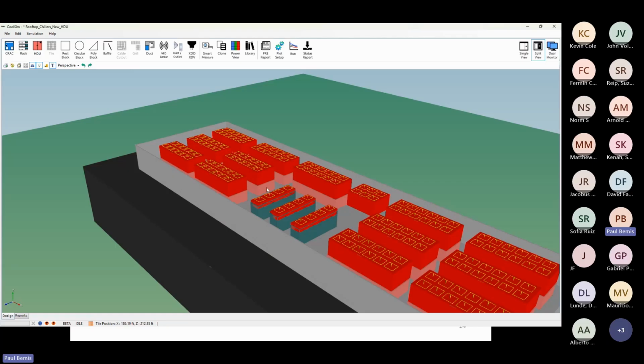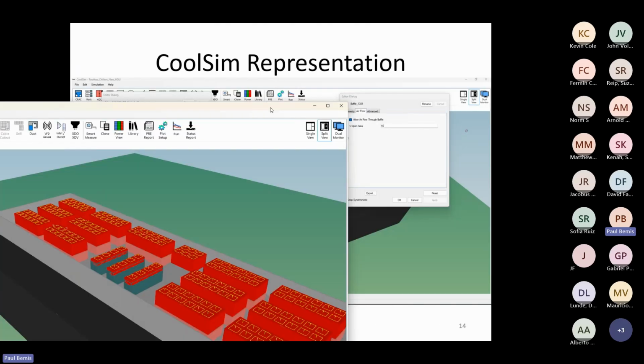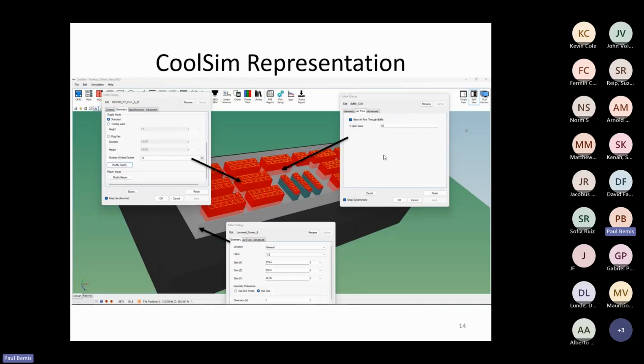These devices already will have low pressure in the bottom because they've got fans pulling them up. So I'm going to show you shortly, there's low pressures being generated at the bottom of these devices caused by their inlet fans. Remember, these are 10,000 CFM a piece, and you've got 12 of them, and 12 times N. You've got a lot of low pressure down low. That's your enemy. The low pressure at the bottom is going to cause recirculation to occur. So let me put that aside for a moment. I think I covered most of these things.